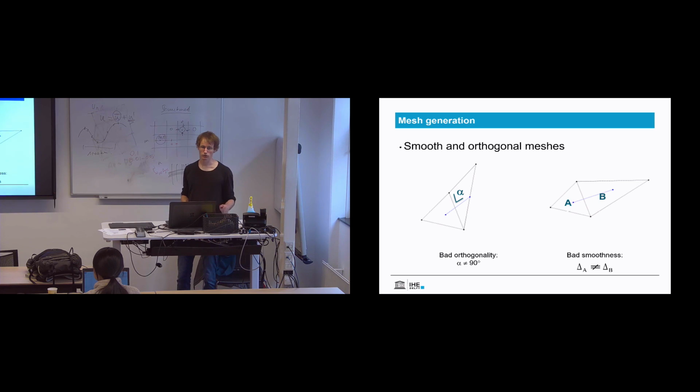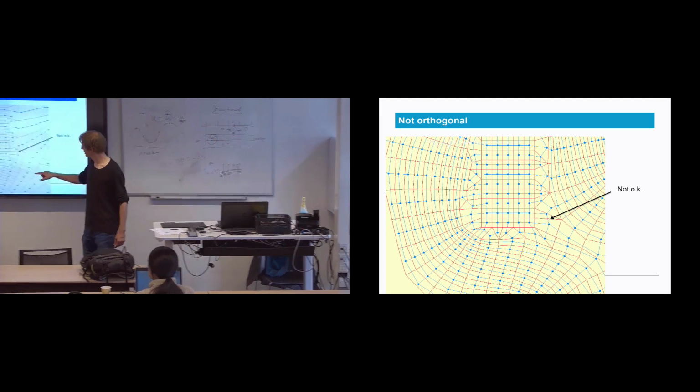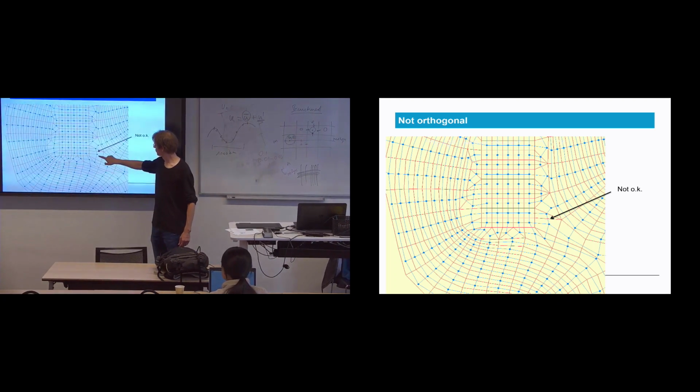Otherwise, you will make errors, or your results will be inaccurate. Very important. Okay, to demonstrate this on a regular mesh. So here you see a link that is certainly not orthogonal. So you see that this is not 90 degrees. There's other examples. This one, this one, this one. What was even here? This one is horrible. Well, you get the point.